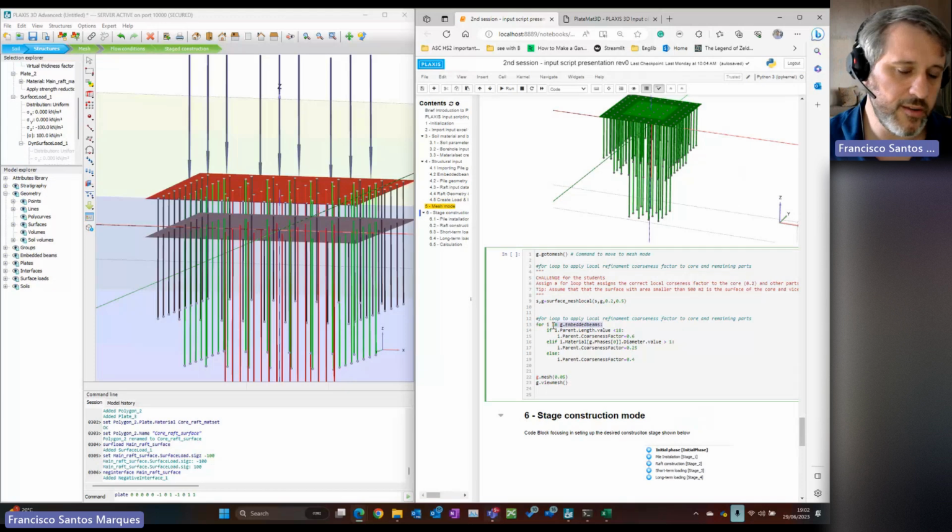So you iterate over all the elements of the embedded beam, and then you say, okay, if the length is lower than 18 meters, then 0.6. But else, if it is not the case, then it's going to check if the diameter is higher than 1, and if it is higher than 1, apply 0.25. If not, apply 0.4. Okay, and then after that, ask to run the mesh, to generate the mesh with the medium distribution, and view the mesh.